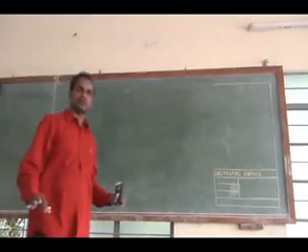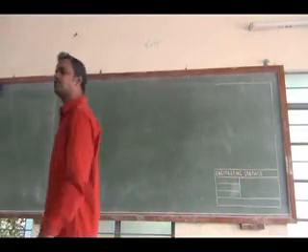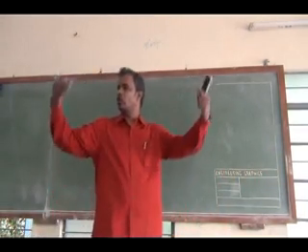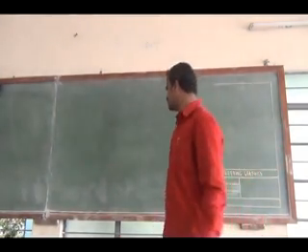The difference is the left side view comes on the left side itself, to the left of the front view, but the whole front view and left side view will come below the reference line. That is the difference.